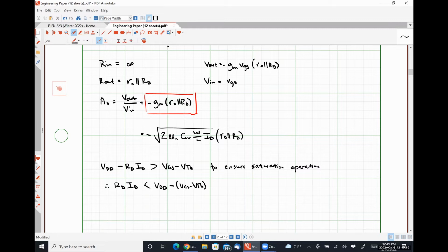The more we increase our gain, the more likely we are to push our device out of saturation. And it comes from the fact that we have this DC current ID flowing through this DC resistance RD, generating a potentially higher voltage drop the higher the gain is, okay? So we're limited by our power supply voltage as to the maximum gain that we can achieve, okay? Now, to get around this headroom constraint, circuit designers have come up with a couple of interesting solutions.